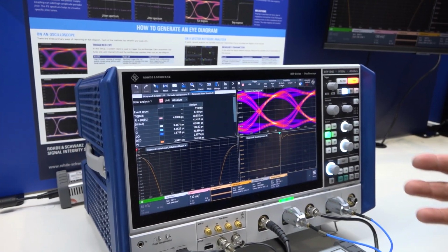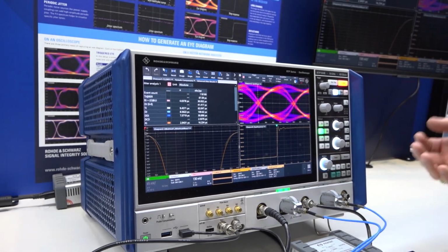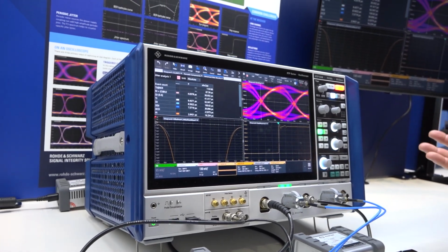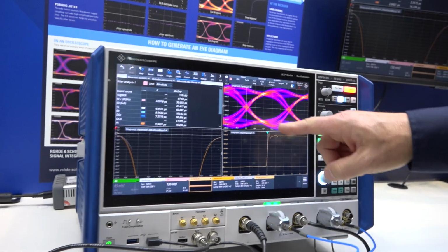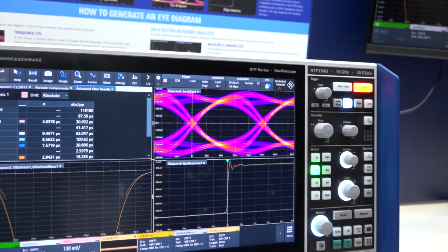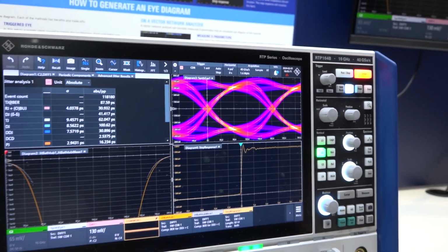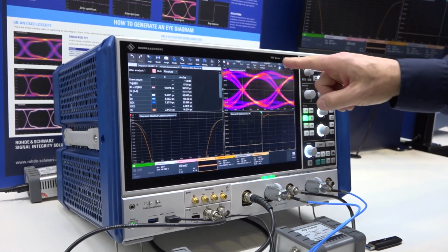Here we have an analysis of drive number 2. This is the one that really had the rather ugly looking eye pattern. As you can see, this eye pattern we call synthetic eye on the top right shows the characteristics that we were noticing when we looked at the live eye, that overshoot.